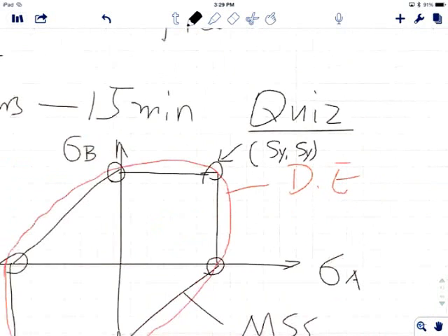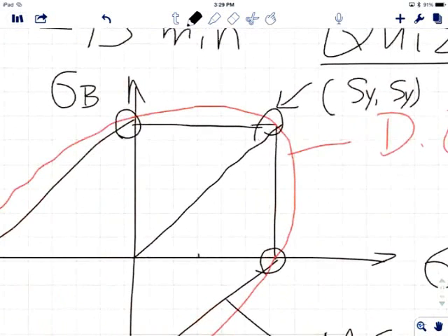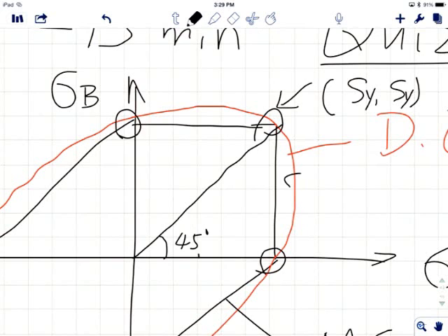In the x-axis, it's sy. In the y-axis, it's sy. So if you draw a line to connect them, your stress state for question A is on this line, because this line has angle 45, because this is sy, this is sy. So what you have just now is 70 and 70, right? It's right on this line. Later on, I'm going to tell you why.